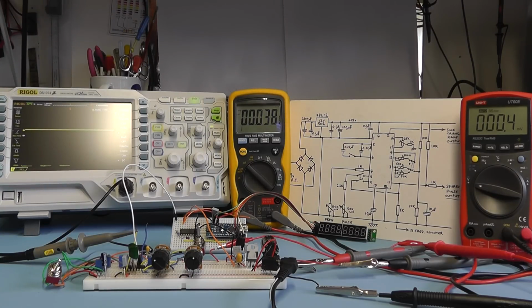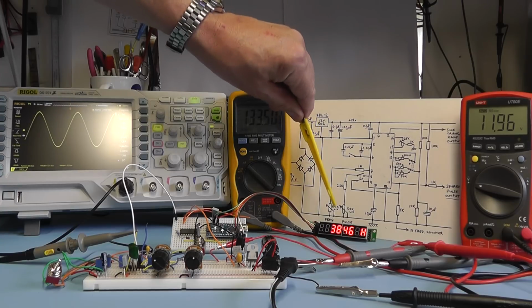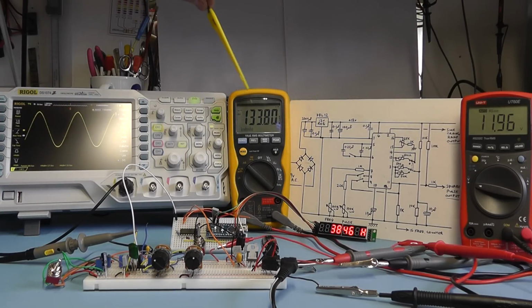So now let me switch on the power with the 12 volts AC supply going in and just see if that solved the problem. Right, well, the function generator seems to be working fine. There's no noise now or clipping on the waveform. The frequency counter is working okay. The current being drawn now is hovering around 130 milliamps or so.